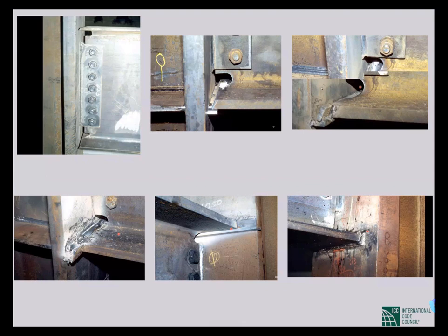These are step-by-step construction steps, basically welding steps: how the beam flange should be welded to the column flange for a CJP weld, complete joint penetration, in a special moment frame. So suppose we start with the top left picture. There we have the beam, but this is not the complete joint. The joint is not complete yet.